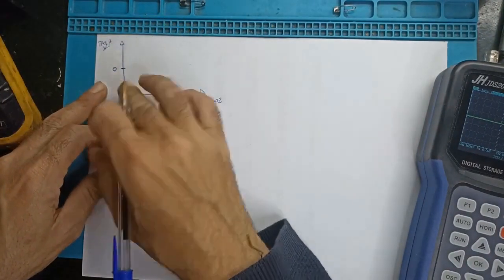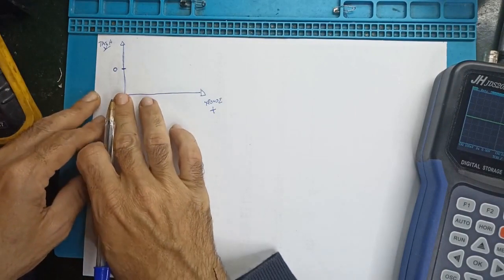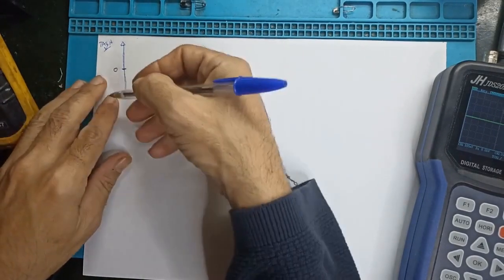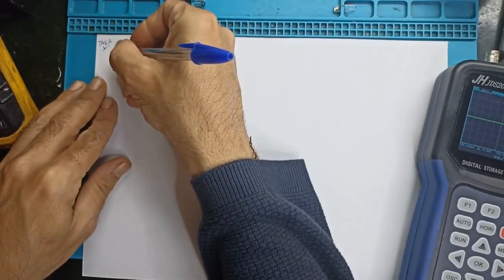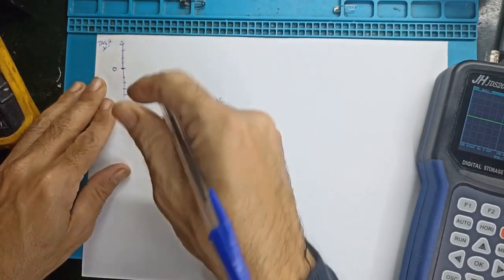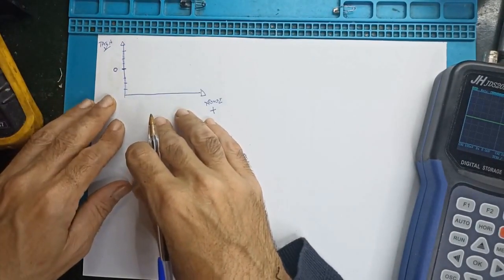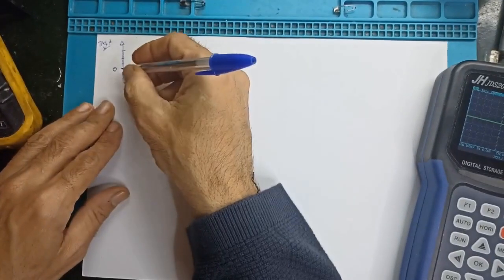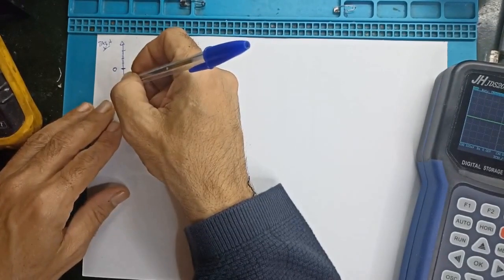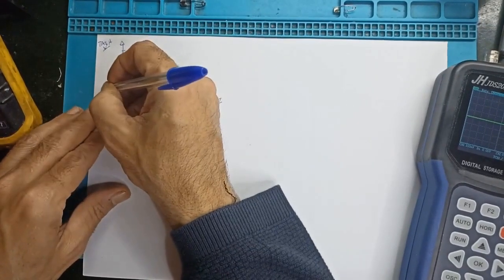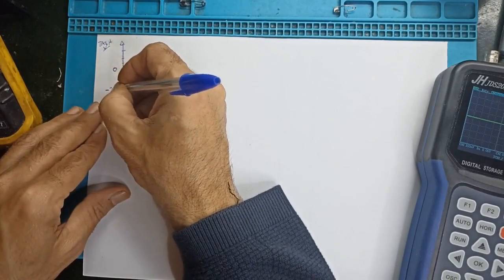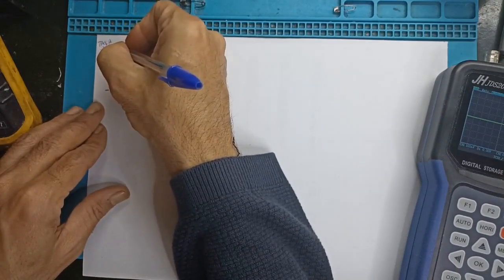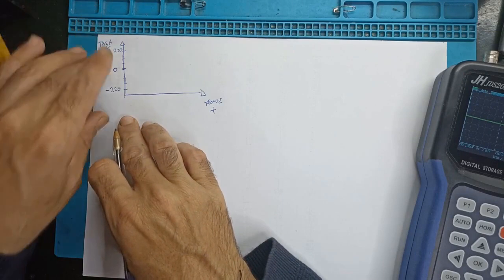I will use the voltage of the network that we have here in Greece, 220 volts, to show you exactly how it is represented on the oscilloscope. On the axis we have zero volts in the middle, the positive values towards the top, and the negative towards the bottom. In the negative values, down, the minus 220 volts will appear on the oscilloscope, and in the positive values, up, the plus 220 volts that is in our network. We get plus 220 and minus 220 volts, which tells us that we have 220 volts in the alternating current. This is understood as peak to peak.